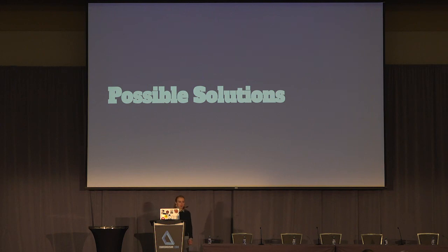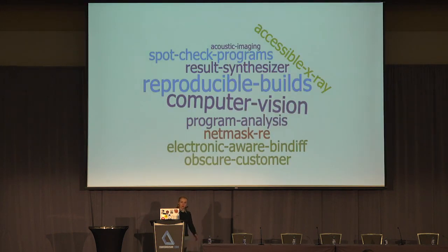All right, so possible solutions. There you go. Computer vision, machine learning. I do think that there's more room to be done on automating the reverse engineering process of these IC components as well as the actual board itself. So one thing that I really do want to see is better tooling around lifting netlists off boards, looking at the integrated circuit connects. We need the ability to automatically trace or compare lifted netlists or X-rays between each other.